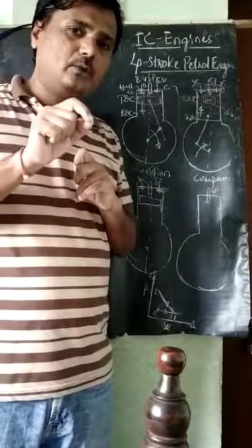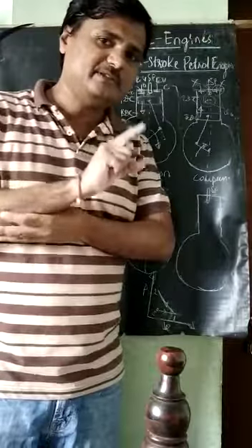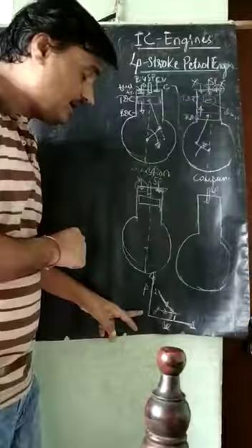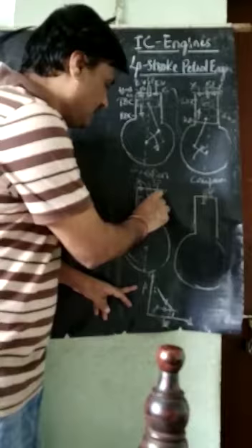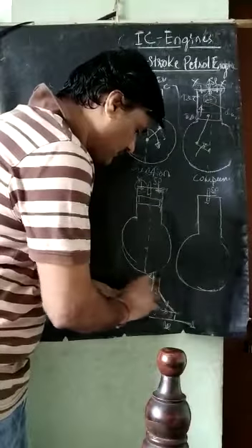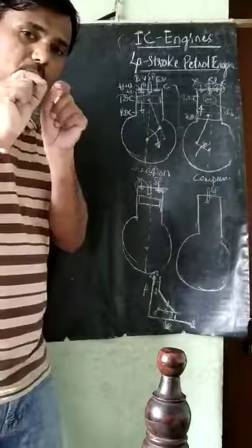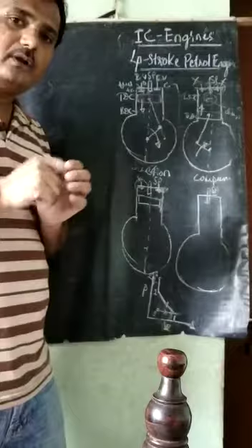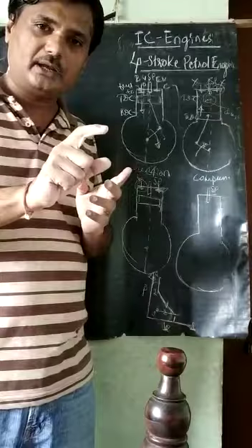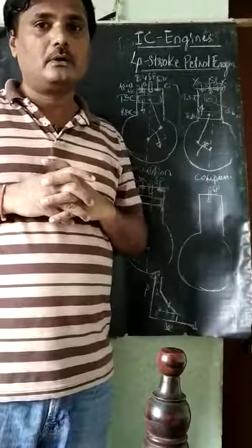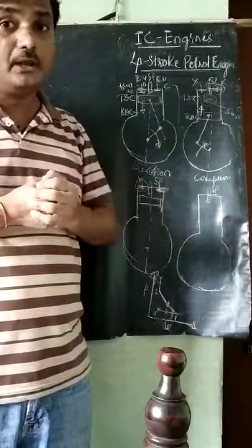So that the spark will be generated. That is called the heat addition process. That spark will be generated at a constant volume process. So when the piston is at top dead center, at a constant volume process 2 to 3, heat is added and the spark takes place. Once the spark has been added to that highly compressed charge, what happens? The flame will propagate, the combustion reaction will start, and a large amount of heat will be released.